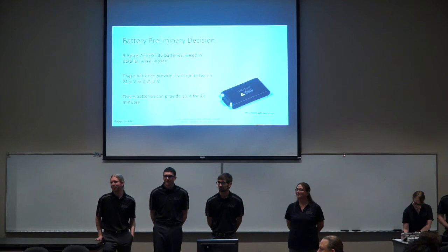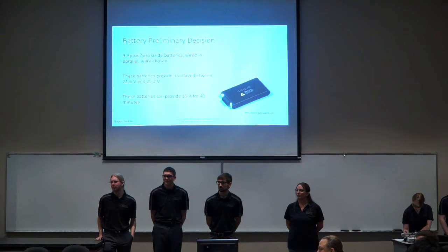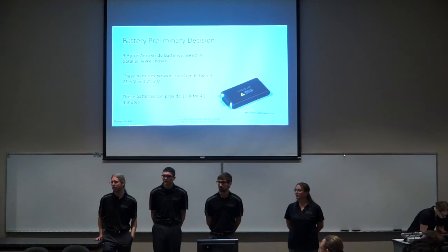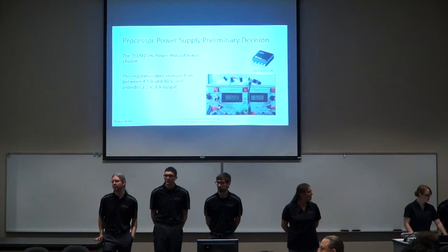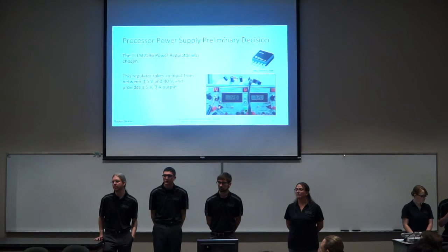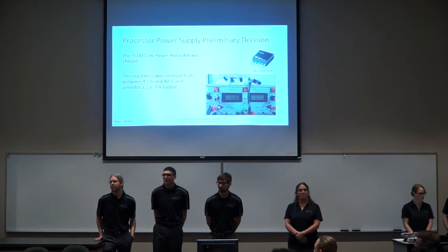Okay, so you might want to talk to Professor Kodemer. I know he's worked with some other teams on that, but especially with the lithium ones, they can be unstable if you put them in the wrong conditions. Second thing, you talked about the power regulation. What kind of regulator is that? For which? The LM2596 that you selected, is that a linear regulator? That is a buck converter. Buck converter, okay. And you listed voltages. Did you look at power consumption and how much would be absorbed by that? From the power consumption of, can you please specify? Yeah, I guess my question is, are you going to have to heat sink that for power dissipation?